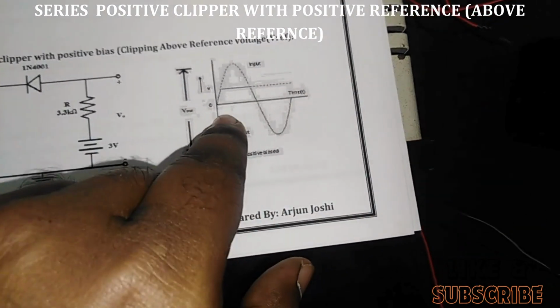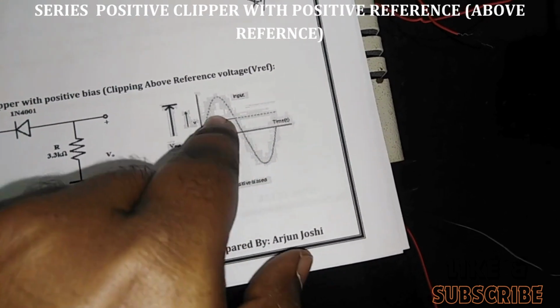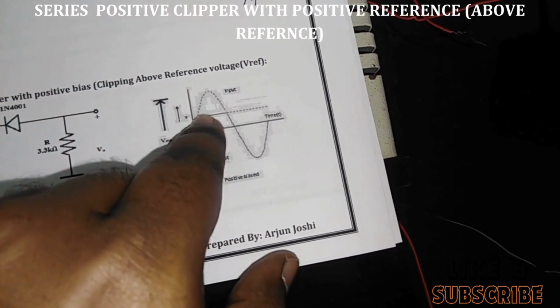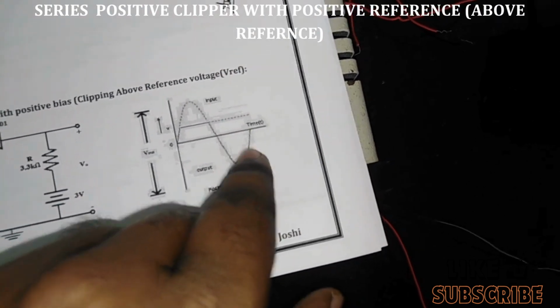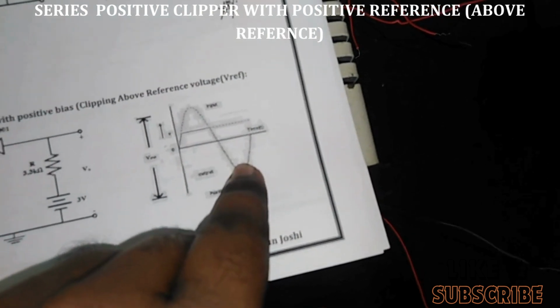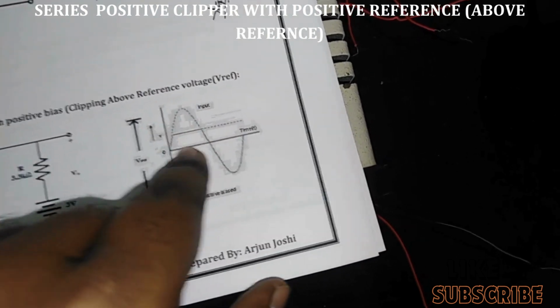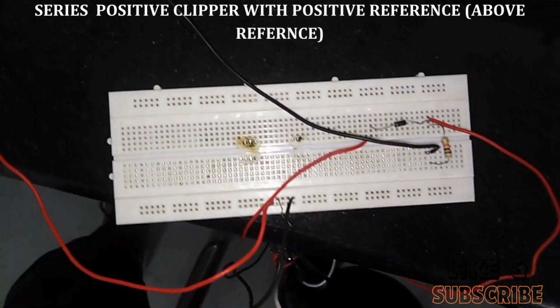Okay, this is the expected output waveform. The 2 volts should be clipped off. V naught is equal to Vr. Here in the negative half cycle, V naught is equal to Vi. Whatever there is in the negative half cycle, that will be reflected in the output side. So we need to concentrate on only the positive half cycle. Okay, now let's get into the breadboard connection.